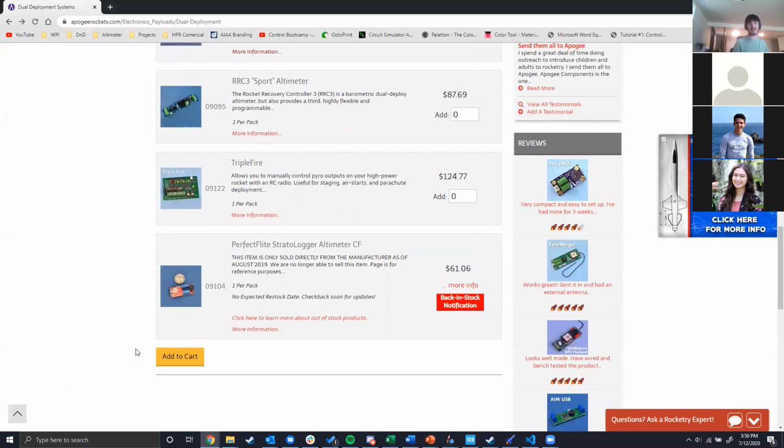And finally, there's one thing that I didn't mention, being timers. You can buy timer boards, which essentially is like an altimeter in that it will detect your launch, and then rather than firing something at apogee, it just fires a charge or whatever's connected to its terminals at a set time, and that's typically used for lighting a second stage motor, which I think in general I'd probably discourage you from trying to do a staged rocket as your L2 cert, but yeah.